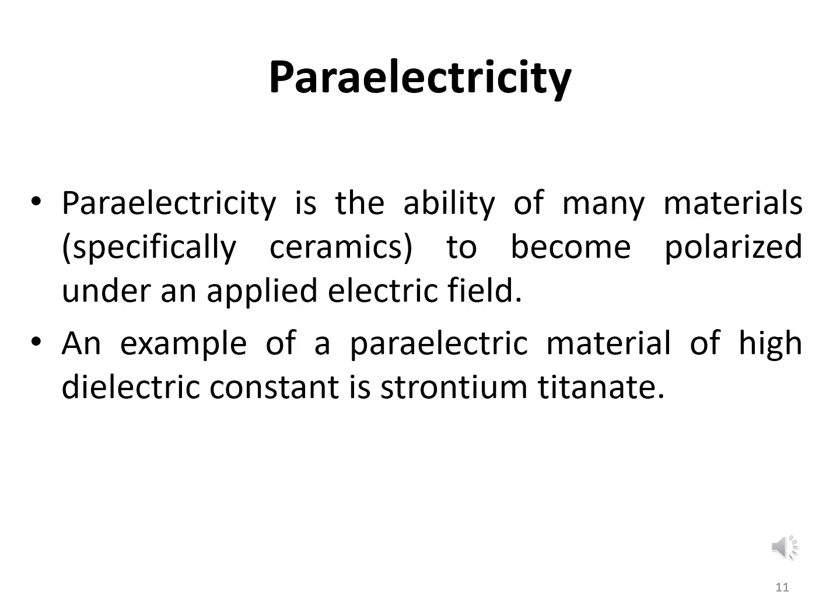So this paraelectricity occurs in crystal phases where electric dipoles are mostly unaligned, and thus they have a potential to align in an external electric field, and they can weaken it. An example of a paraelectric material with a high dielectric constant is strontium titanate.